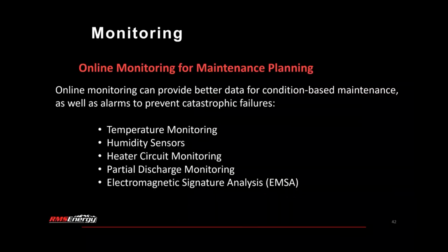So some of these online monitoring systems can be temperature and humidity sensors, measuring the ambient within the bus. You can have heater circuit monitoring to make sure that your heater systems are in functioning condition. Partial discharge monitoring is also becoming popular. And then newer technology like electromagnetic signature analysis, or EMSA testing.